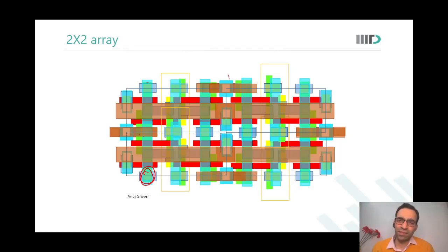See, if mask preparation and optical proximity correction were so simple, Faisal, they would have allowed everyone to use the degraded DRCs. They allowed only you because of the repetitiveness of the structure. But it still meant that they are pushing the limits of the technology. Okay, due to that pushing of technology, there may be yield loss. There will be yield loss.